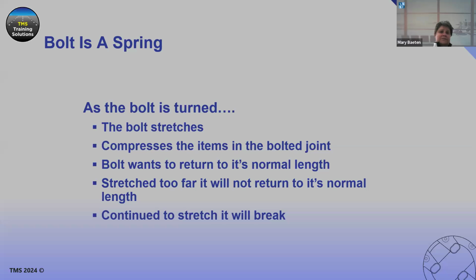Again, as Seb said, the bolt acts as a spring. As the bolt is turned, the bolt stretches, elongates, and it compresses the items in the bolted joint. The bolt wants to return to its normal length, but if you stretch it too far, it won't return to its normal length. And if you continue to stretch it, it will break.